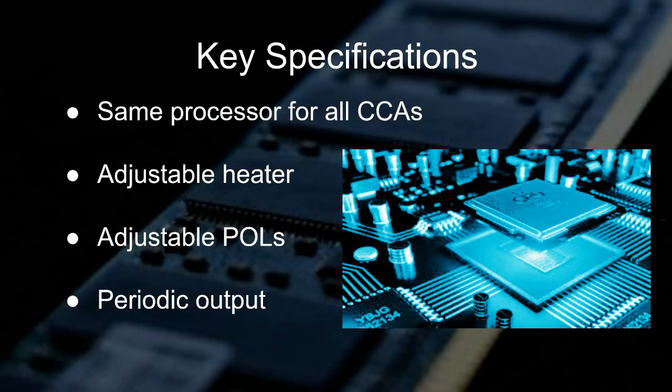And so we ended up settling on processor choice of the Zynq UltraScale so that we would have an FPGA and a processor side so that we would be able to communicate with the processor side memory via the processor, and it would run the program from that. And then the FPGA side would be used to communicate with our DUT memory that would be tested for the memory interfaces that would need that extra DDR interface.